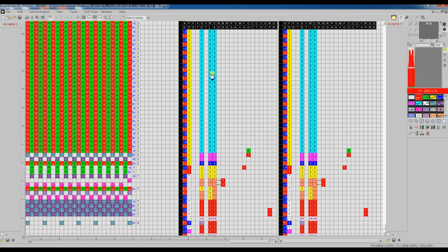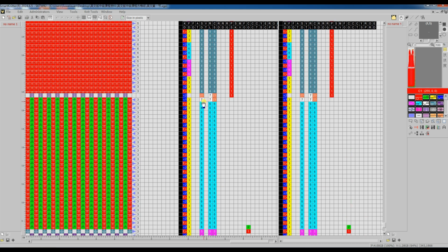The sweep can then be knitted with 1x1 ribs. Here you can see the speed and roller number are both set to 6 at the sweep. At the last course of the sweep, the tension number is changed to 7 for easier adjustment on the machine. Usually the last row is looser than the sweep to facilitate transfer to the body structure.